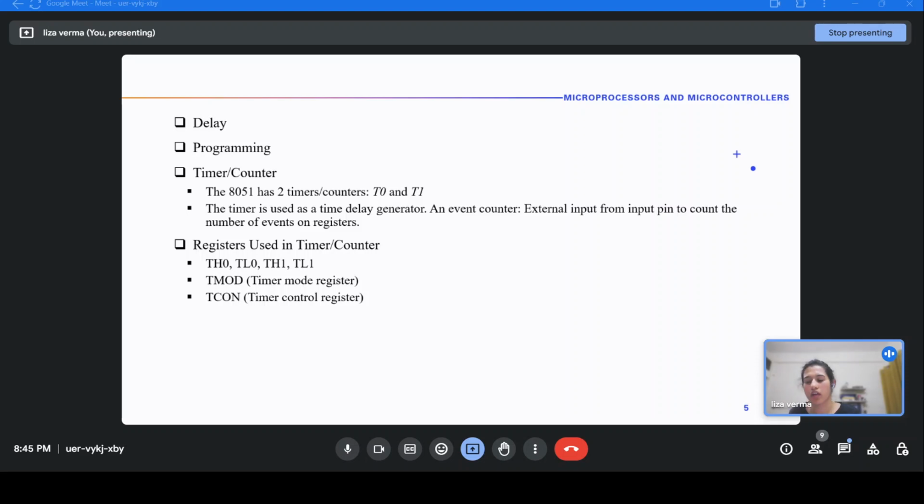It doesn't have a timer overflow flag, but it can still keep working as a timer internally. But it has lost its connection from the outer world because its timer overflow is being used by TH0. I don't know if you understood it, because if I had diagrams, I would have shown them.